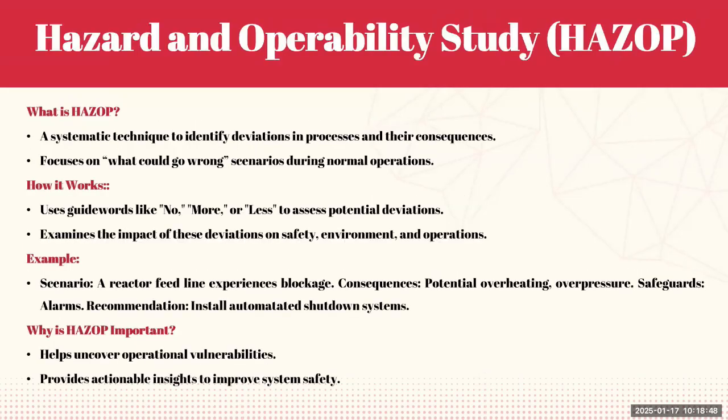Then we have the hazard and operability study, HAZOP, which is a very, very important study, and every process plant more or less would need to do this HAZOP study. So it's a structured approach to identify deviations in processes and assess their consequences. Essentially, it helps answer the question, what could go wrong? What could go wrong during the normal operation?